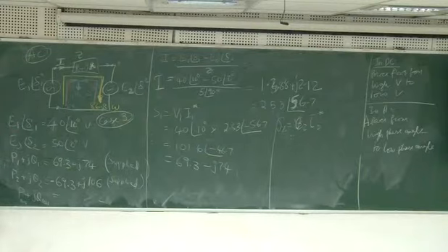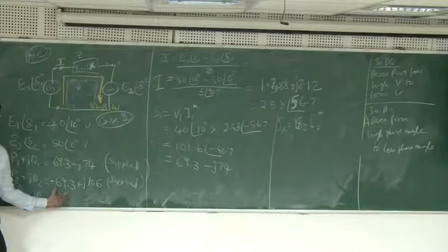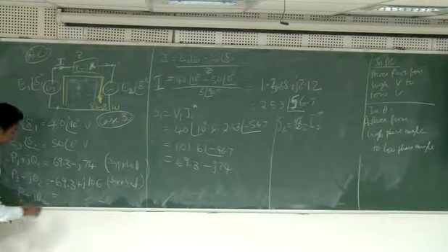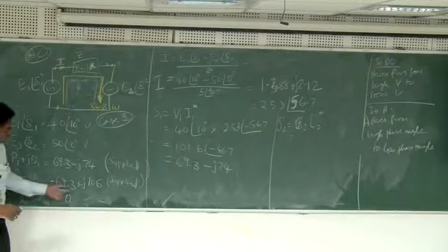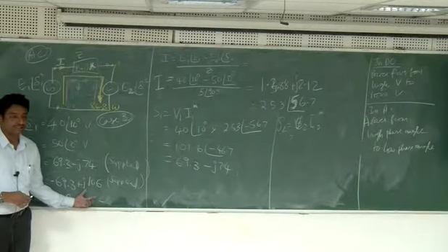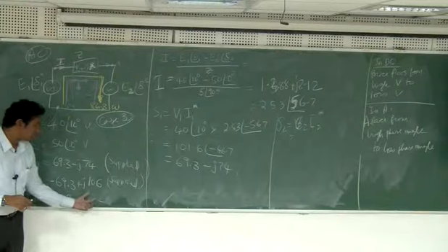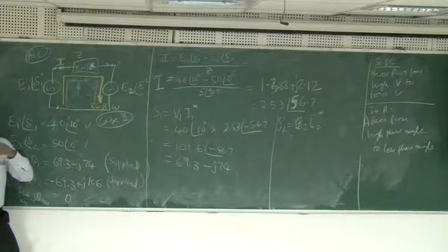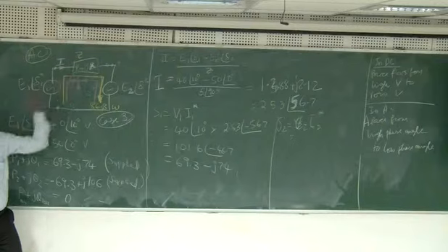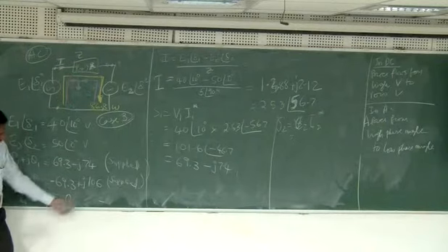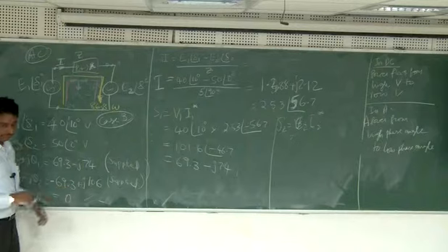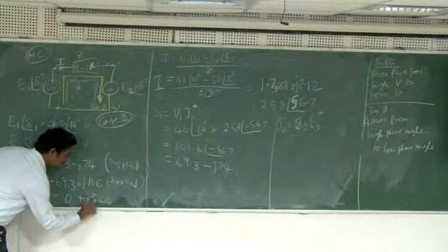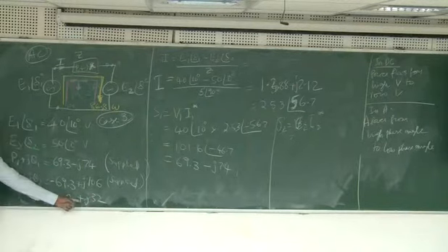Okay. So what you notice is the second source is receiving plus 69.3 watts. So this is 0 because there is no losses. Whereas the supplying part, it is supplying 106 watts. Okay. Out of 106 supplied, 74 is received at the source 1. Therefore, the remaining must be consumed at the line itself. Okay. So we will verify that. So what is the difference? 106 minus 74, 32 plus J32. Okay. So the Q loss supposed to be J32.